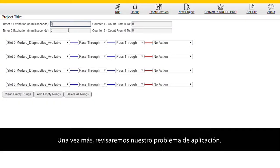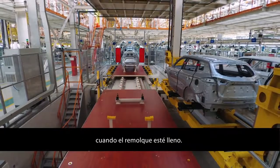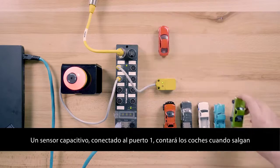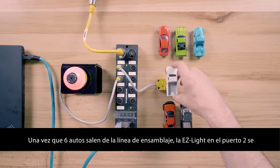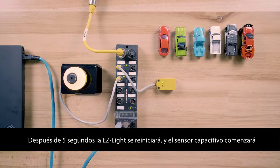Once more, let's review our application problem. An automotive company producing cars needs to notify the truck driver when the trailer is full. The truck trailer has a capacity of 6 cars. A capacitive sensor plugged into port 1 will count cars as they leave the assembly line. When 6 cars leave the assembly line, the indicator light on port 2 turns on, telling the truck driver that their trailer is full. After 5 seconds, the light will reset and the capacitive sensor will start counting cars